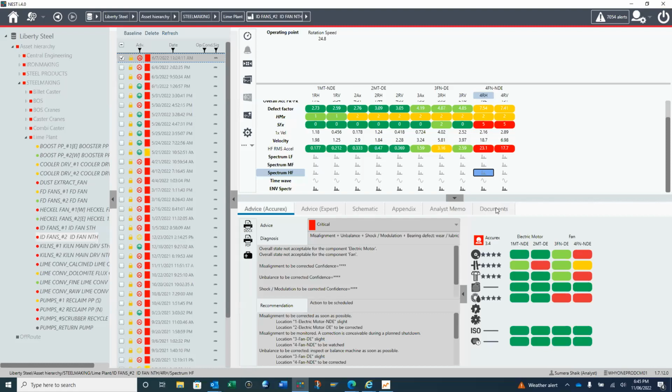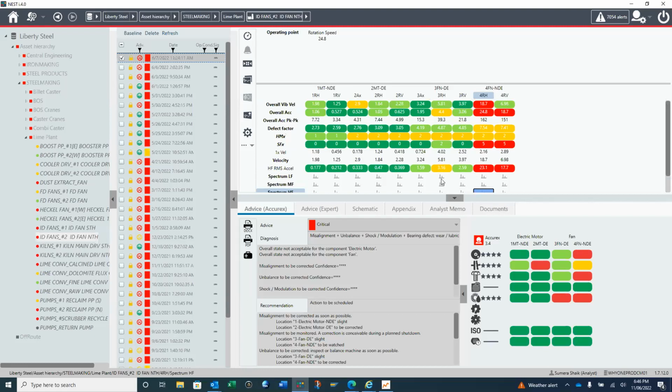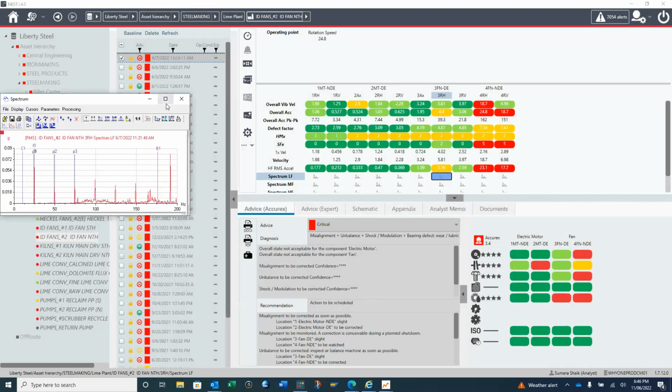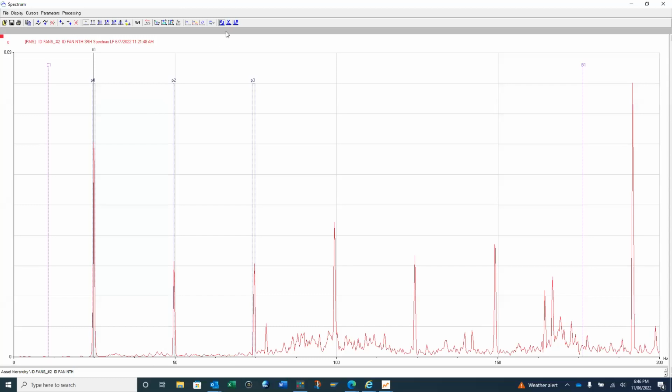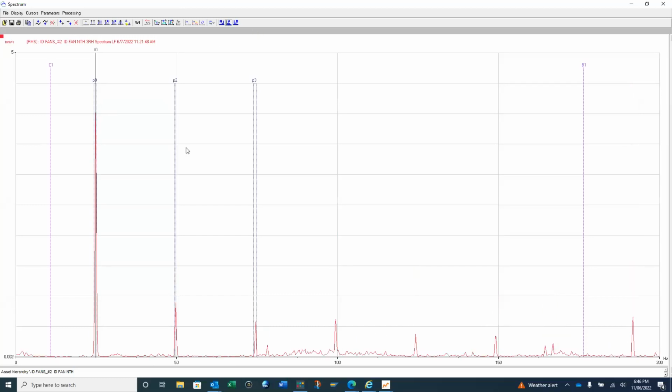Do you think I should take this again? Try to check this again. Maybe the 1.25 hertz is sometimes there, sometimes not there. If the trend is sometimes there and sometimes not there, then it is not a true vibration of the equipment. Okay.